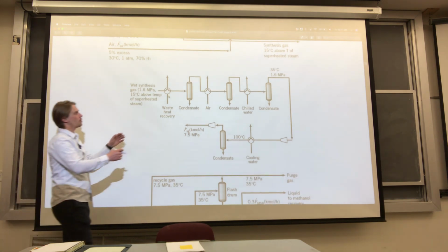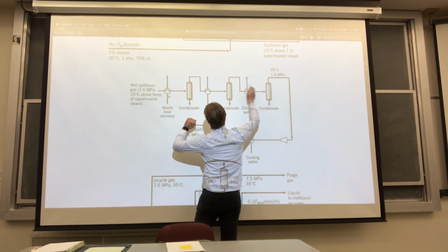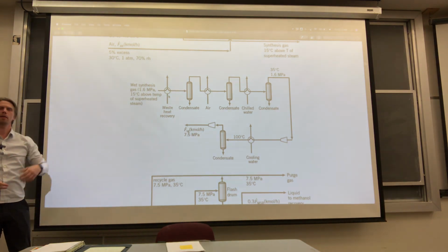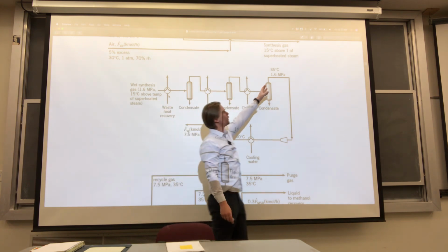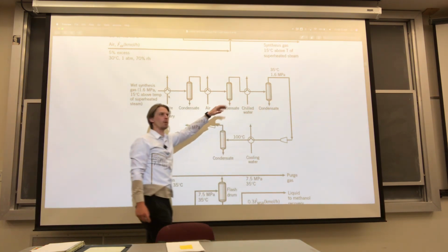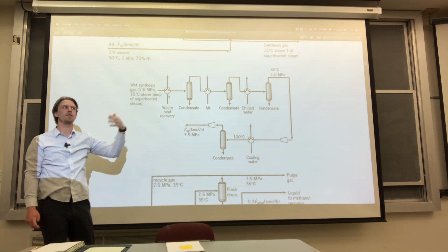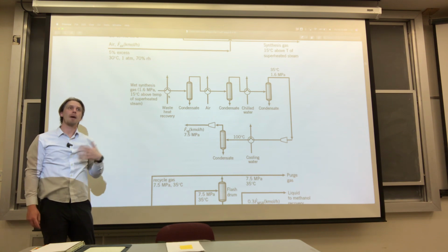So in the last part, you lumped all of these together, right? So you went from 35 degrees C to whatever this initial temperature was that you didn't have to worry about. Now you do have to worry about it. And you determined what is fully saturated water at the vapor pressure of water at 35 degrees C. And then from the material balance, you figured out how much water had to be removed. So now what you need to do is work backwards.